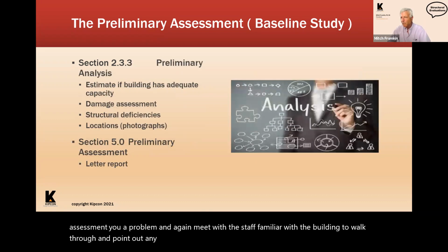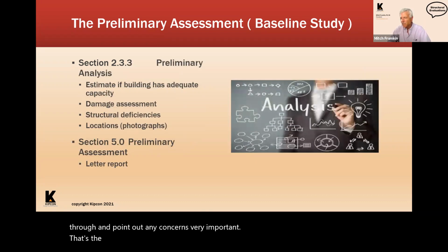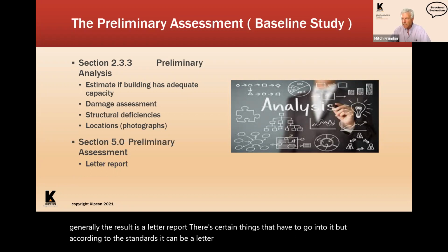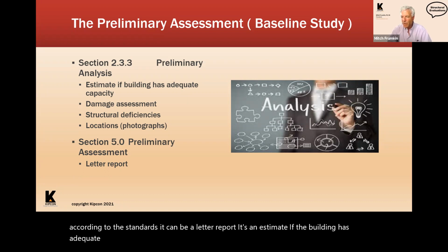Very important. Next, the preliminary analysis. And I'll jump to the bottom. The preliminary analysis is generally the result is a letter report. There's certain things that have to go into it, but according to the standards, it can be a letter report. It's an estimate if the building has adequate capacity. If there's a problem, it gives a damage assessment, identifies structural deficiencies.